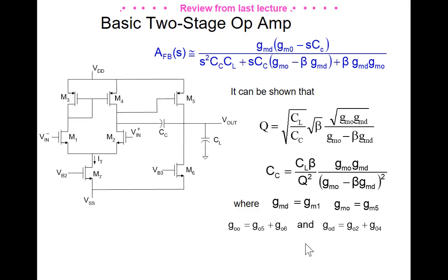If it makes the S term smaller, we have to make a bigger compensation capacitor to get the term big enough so that we have the right pole locations. Okay, so this right half plane 0 has hurt us. It's made the compensation capacitor become bigger again to compensate for the reduction in the term because of this negative term here.